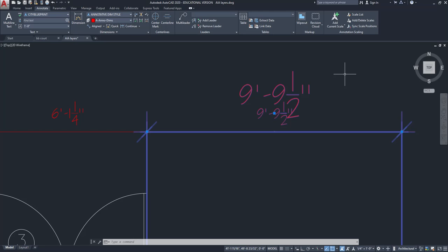We'll say in the dark ages of AutoCAD, when you created a dimension style, you had to create about 10 of them before annotative text, because we had 1/8 inch, 1/4 inch, 1/2 inch, 1:1. We had a bunch of different very common scales that we used, and AutoCAD didn't use to sort of flex the text for us.